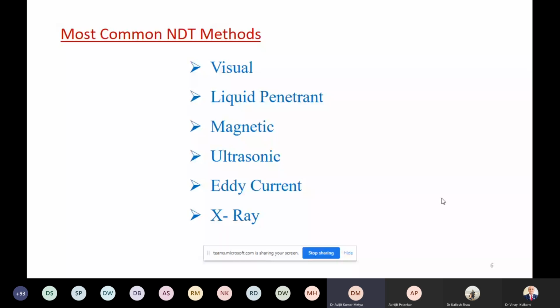That is one of the electromagnetic techniques, which is very, very sensitive to surface or subsurface defects and very minute cracks, which cannot be detected by other techniques, but eddy current can give you a signal if something is there. And then X-ray, using radiography. But the problem with X-ray or radiography is the limitation of the depth of penetration, which depends on the material. But I will be talking mostly about ultrasonic NDT techniques. I will talk about some basic ultrasonic techniques.